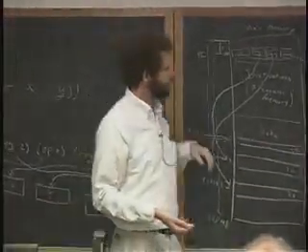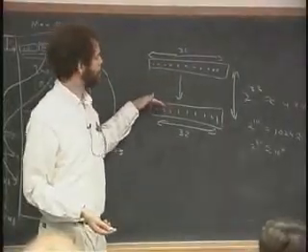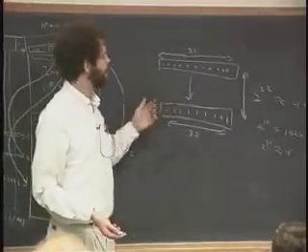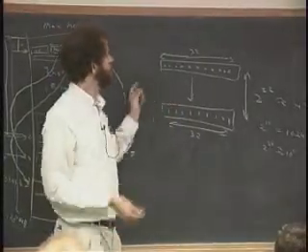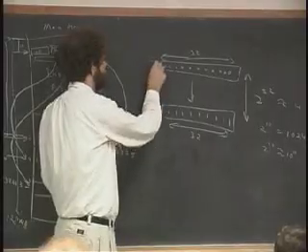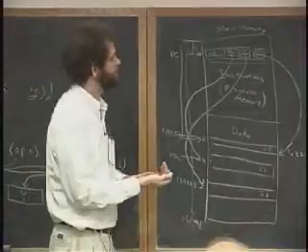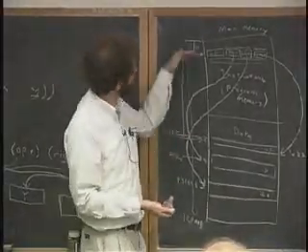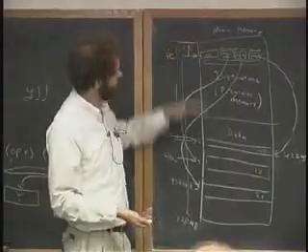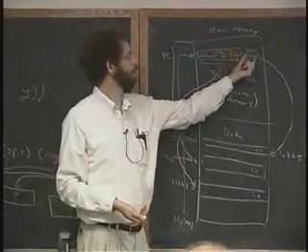So this is 4 giga locations between here and here. That is a typical memory system that you see out there, 32 bits wide. There are some now that are actually 64 bits wide. That's even more. And unfortunately, if there are 2 to the 32 locations between here and here, it means that each of these fields needs to be 32 bits wide.